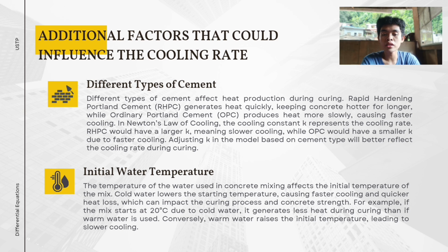Now when mixing concrete, the temperature of the water added can influence the initial temperature of the concrete. For example, if you use cold water, it can lower the starting temperature of the concrete mix. This can lead to quicker heat loss and may affect the curing process. Understanding the curing process and managing the temperature is key to building long-lasting structures.